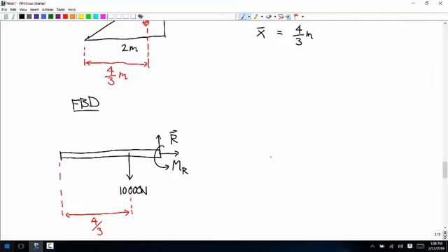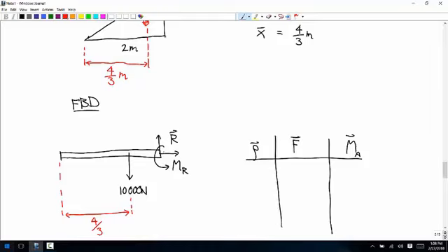And now, when you're dealing with beams like this, horizontal beams, which we're going to do a lot, it's not too hard to just eyeball what these moments are. So I'm going to do this 2 different ways. I'm going to first do it with the rho, the force and the moment, and then I'm going to show just how to do it sort of in your head. So rho, force, moment. And let's put the about point over here because that's where we have the most unknown forces.